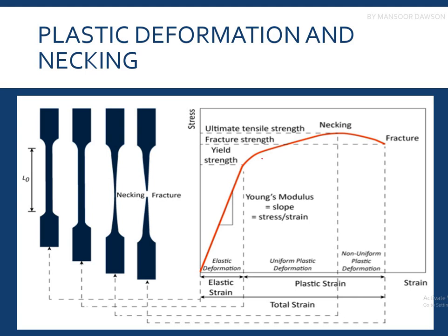Okay, so here is another example of the stress strain curve, explained more clearly. What is happening over here? We can see that this is elastic deformation, and up till this point the deformation was elastic. After this is the yield point or the yield strength, and after that stress, the deformations would be permanent.